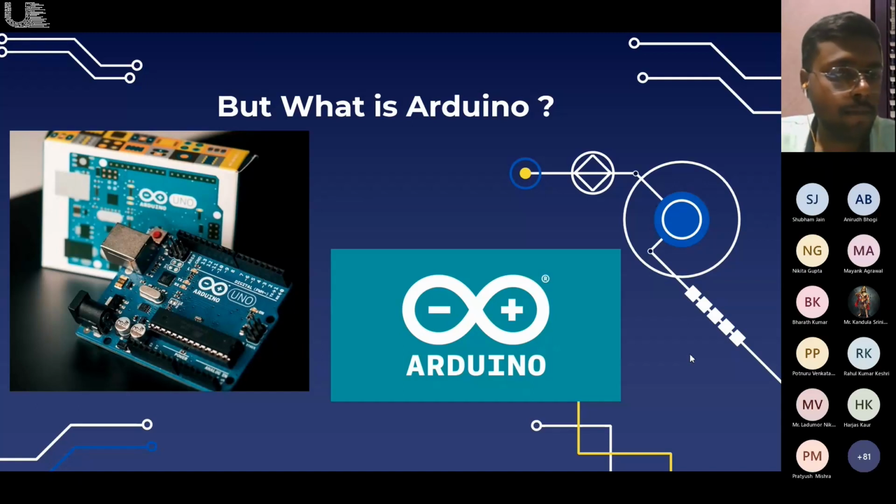The RAM in our PC, the full form is random access memory, and whenever we switch off the computer and turn it back on, so whenever the power is lost, the data on the RAM of a PC is flushed out. But it is not the case with the microcontroller. The microcontroller uses EPROM or EEPROM. This is a type of non-volatile memory, in which the program does not disappear when the device is turned off, and hence it can be continuously wiped and rewritten.